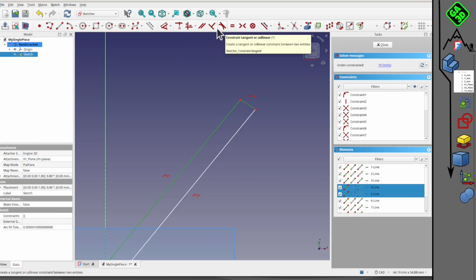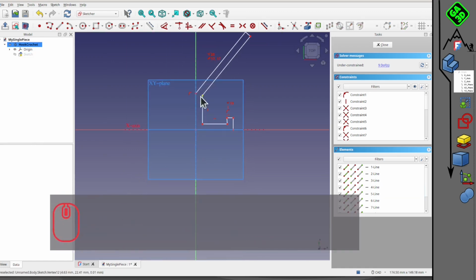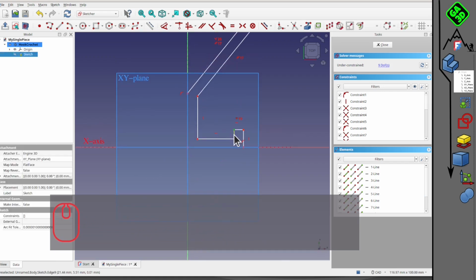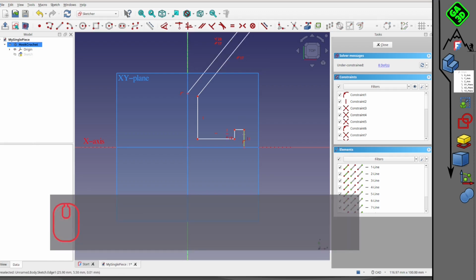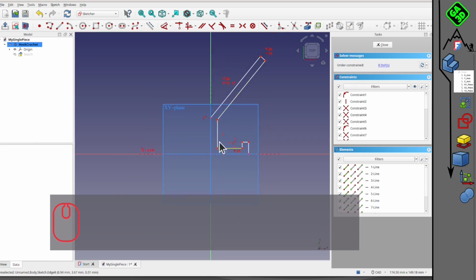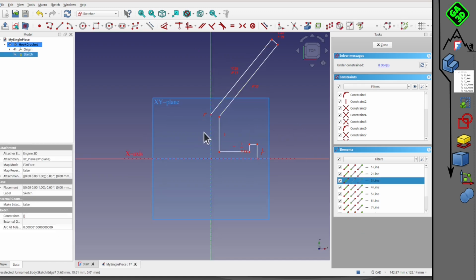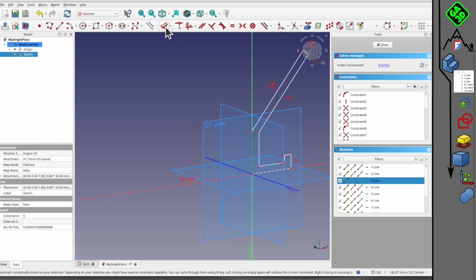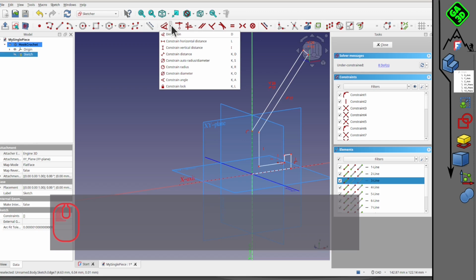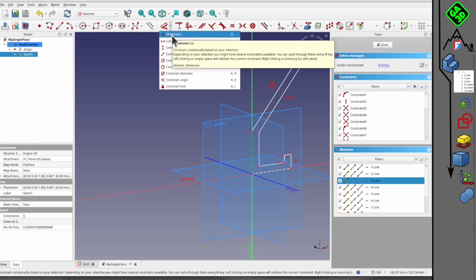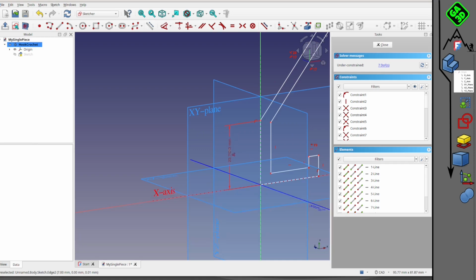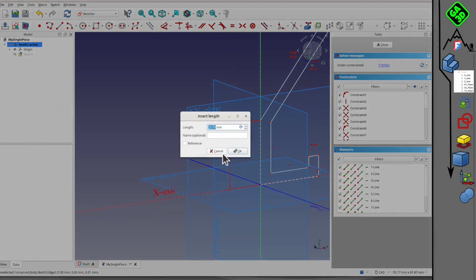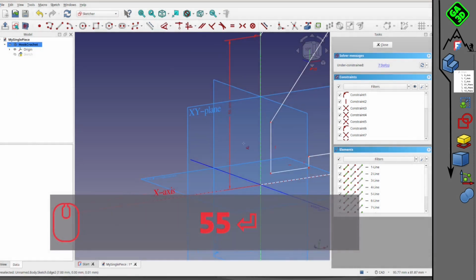Here in this case, we're going to choose the height of this segment. I'd like it to be about 55 mm long. After that, I'll set the total height of my hook. I'd like it to be about 120 mm between the base and the top. So I select the reference axis on which I based myself. Then I press Shift and click on the top of the hook. And we take that tool again, and it offers me directly the height constraint. Now we're 76 mm away. We'll put 120 on it.